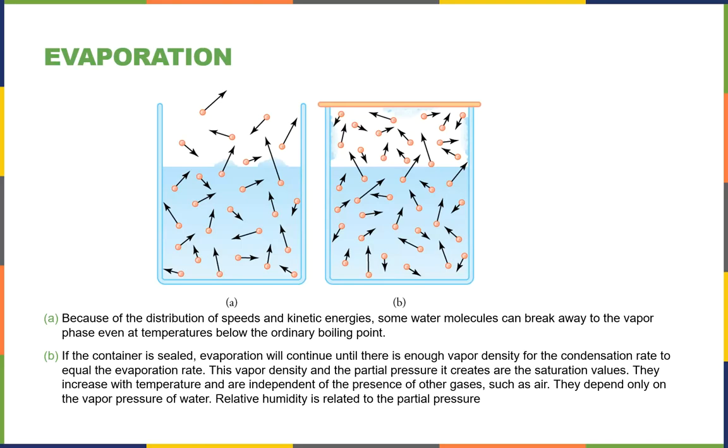In what kind of location would that be really effective? There's some locations where swamp coolers are really effective and some where they're very poor. Florida would be poor. It's in dry places. Places that have names like arid zone. Otherwise known as Arizona. Because it's dry, the humidity is low, you don't have many water molecules that come in, so basically all the water molecules that leave are gone forever. And so you have a lot of evaporation.